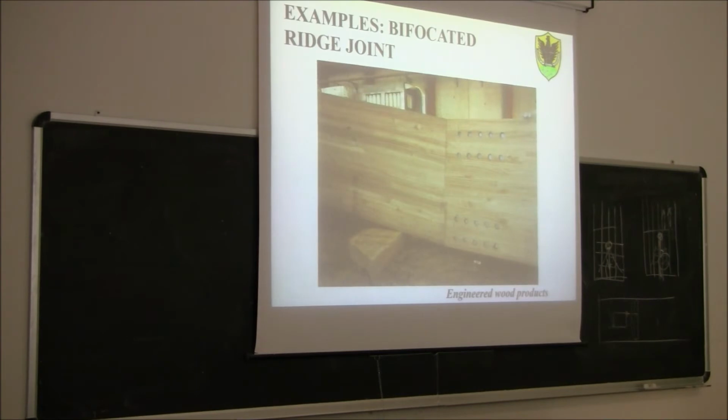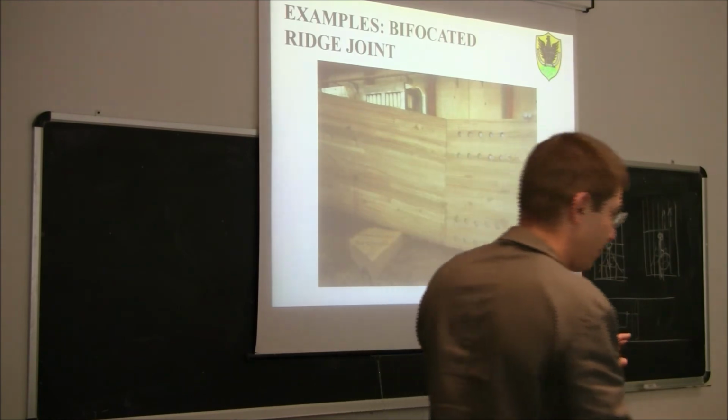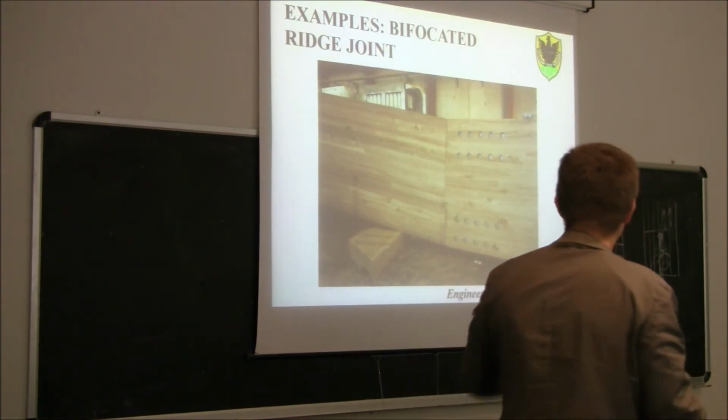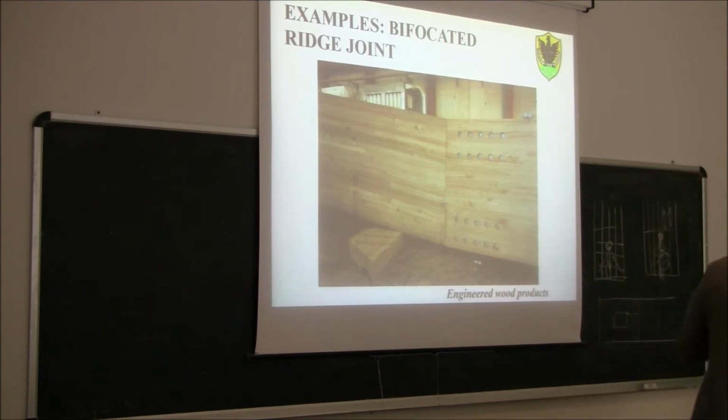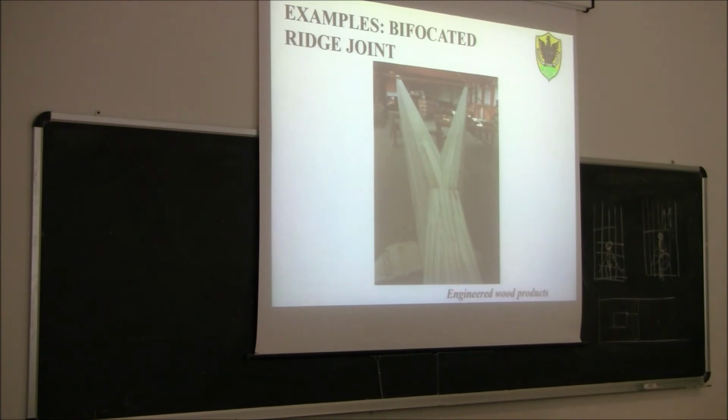You see what they did? Final result, the bolts, and then in order not to see the bolts, to have the nice appearance of wood, what they did also, they put some small elements of wood to cover these bolts. Also here they put some plates of wood, which are of course not structural, just to cover the hole, to give this nice appearance of wood. You see? Now, you don't see it anymore.